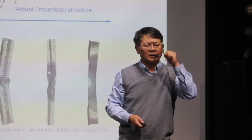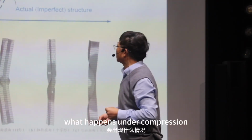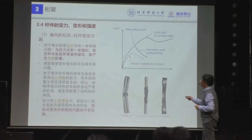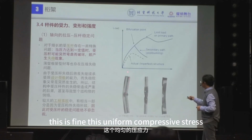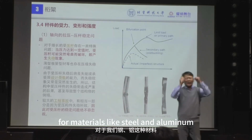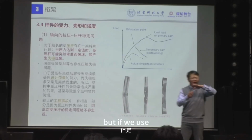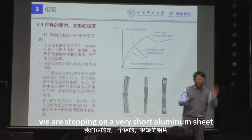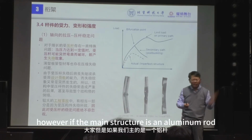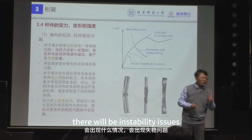Now the key point I want to talk about is this. In frame structures, the most important issue is what happens when a rod is compressed. When compressed, it first generates a uniform compressive stress, which is no problem. We also need this uniform compressive stress to be less than the yield limit. For materials like steel and aluminum, which are typical isotropic materials, no problem. But if the main structure is an aluminum rod, a very long and slender rod, what will happen? There will be instability issues.